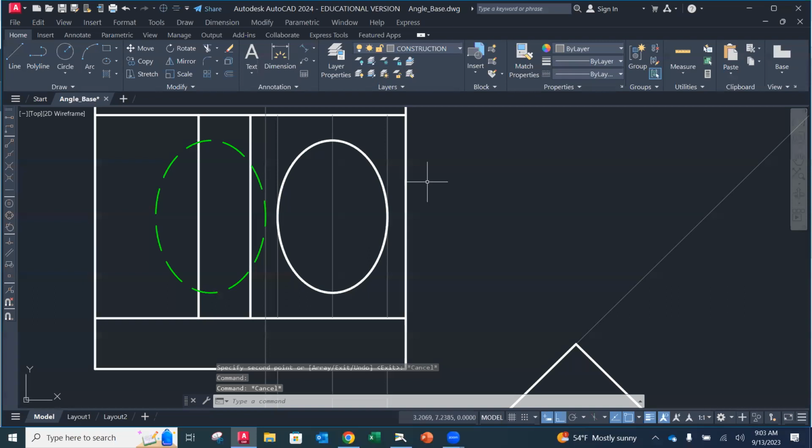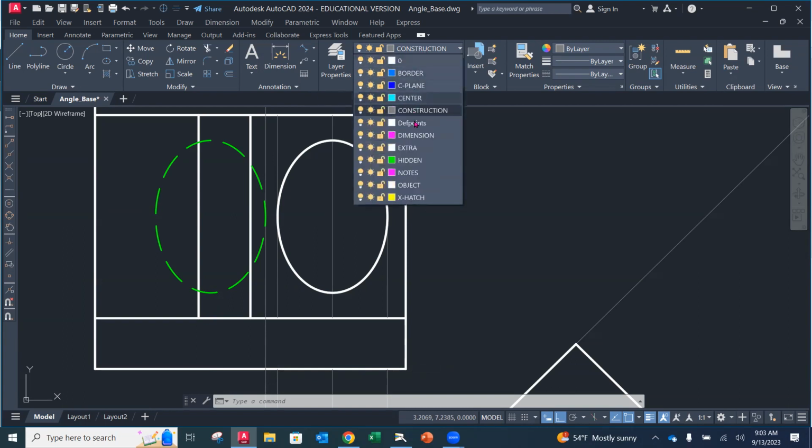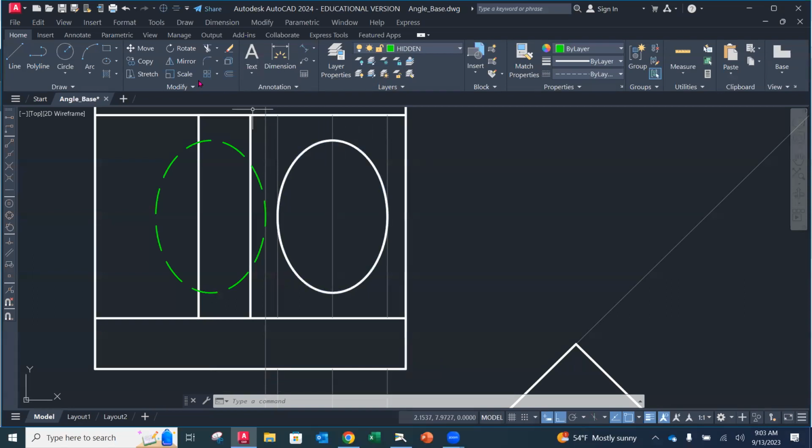There we go. You could completely create that in the very same way that we did before using the hidden lines, or copy it and then put it on the hidden line layer like we just did here. Okay. Now we're going to go back to our hidden lines, and we're going to go to the quadrant up here and go all the way through, perpendicular to that back face where it ends. Same thing on the other side, quadrant, all the way through.